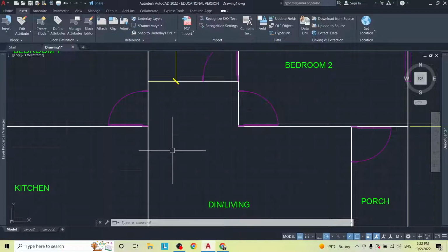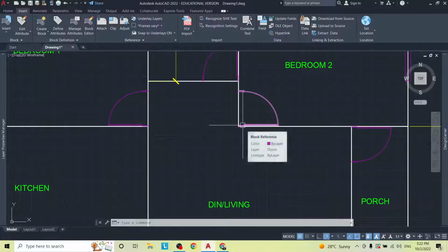All right, so we want 5 feet in the middle of this wall. We want to put a wall straight through here, but we want it to have an arch opening 5 feet in the middle. If the entire thing is 8 feet, that's going to leave 3 feet, split into two sides, this side and that side. So a foot and a half on each side is 450 millimeters. Let's multiply everything by 300 to convert feet to millimeters.